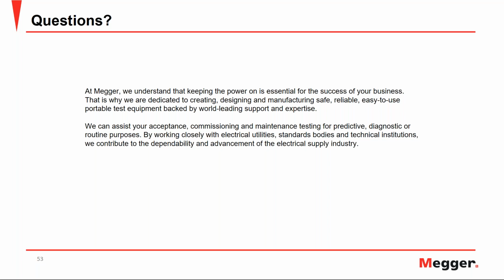And tip-up testing is also another way to get more information. So when you run a power factor test, if you are not looking into the quality of the signal that is coming back from the transformer, you are losing some information. The instrument is doing that automatically for you. It's detecting if there's any possibility of small partial discharges inside the transformer, and it's indicating that you may be able to find out more by running a tip-up test.